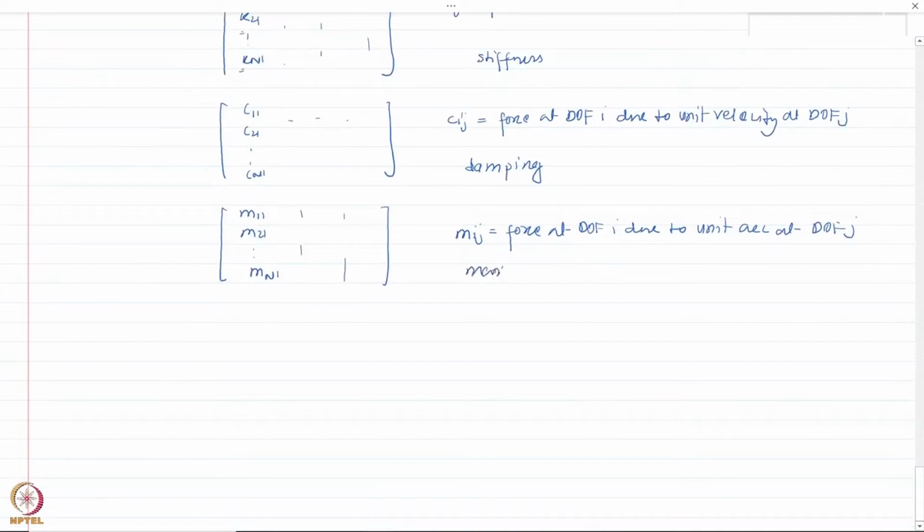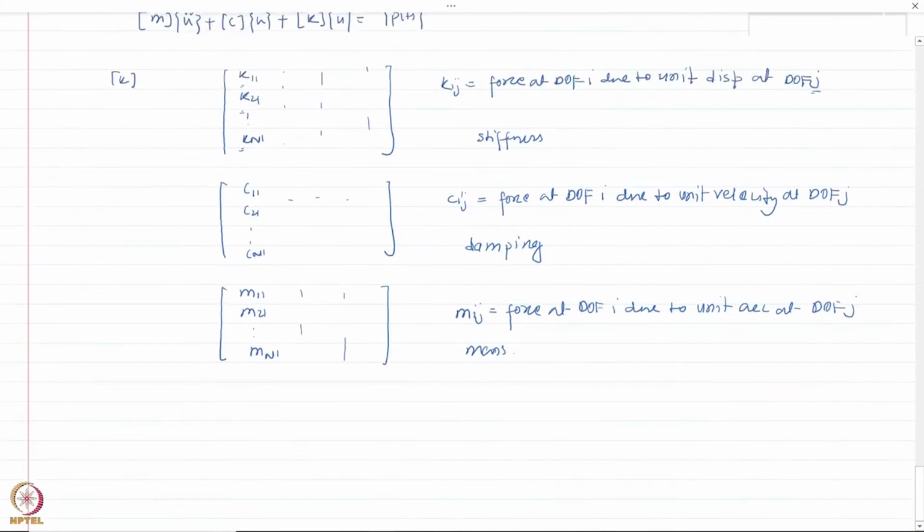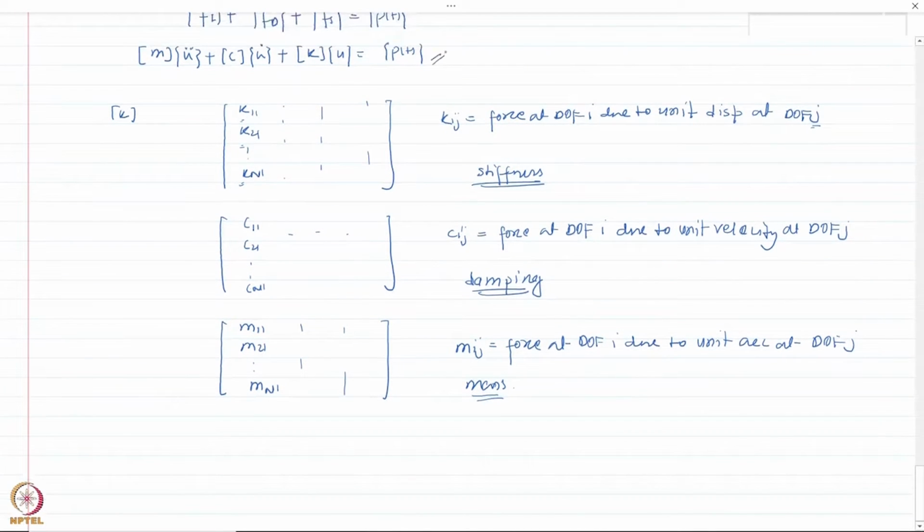Okay, so this basically means that in the stiffness component, we only consider the bare frame. In the damping component, we only consider the dampers, and in the mass component, we only consider the masses in the system without the frame or the damper. Okay, and the representation of a multi-degree of freedom system can be written as a sum of three individual components: the stiffness component, damping component, and the mass component. So using this method as well, we can formulate our equation of motion like this.